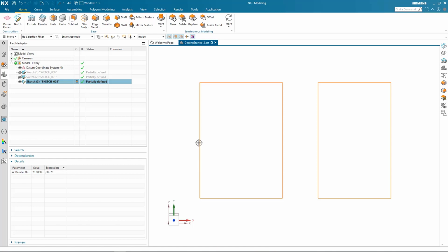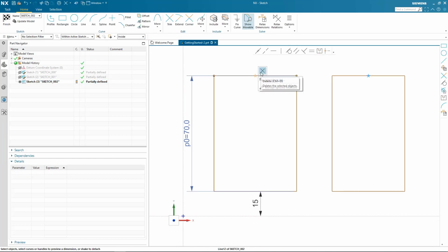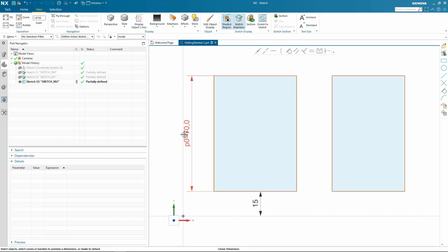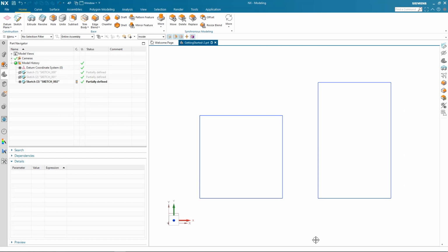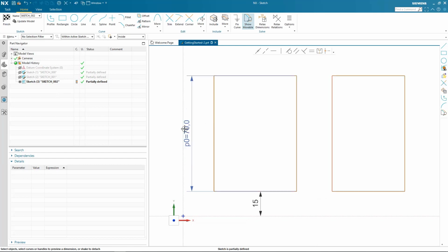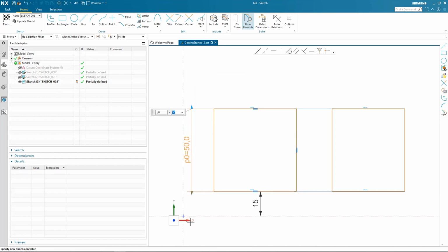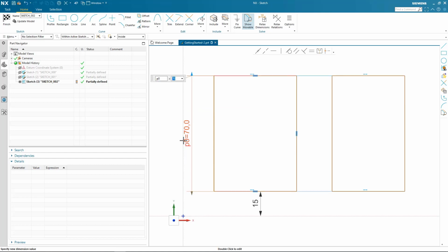There's a bunch of other ways to work around this. Again, now in the sketch environment, I can go back in there and just delete that, and now it will find those. So now I have the collinear relation, but I can override those. This is the traditional way we have looked at it in the past. But now, if I go back, because I just ignored it in the context of changing it, if I change it in my sketch environment back to 70, the collinear relation comes back. This is very helpful to understand how and where the solver finds the relations it needs.